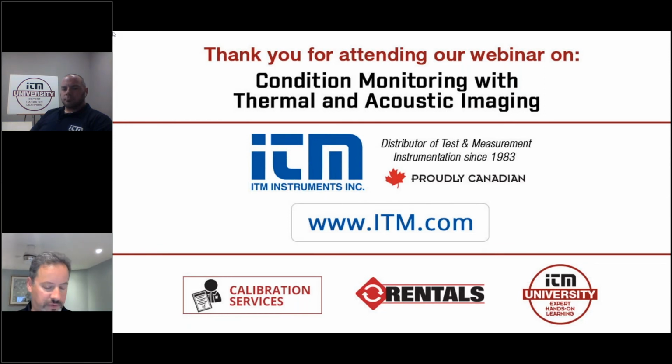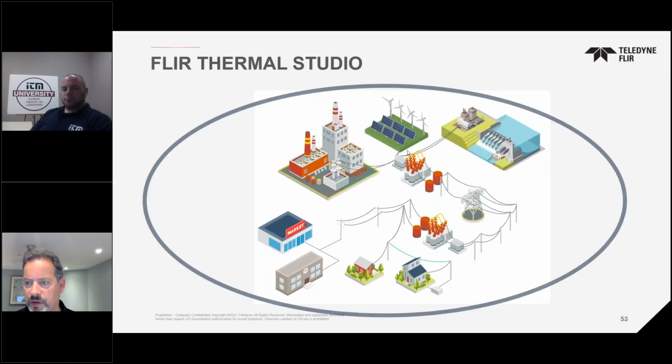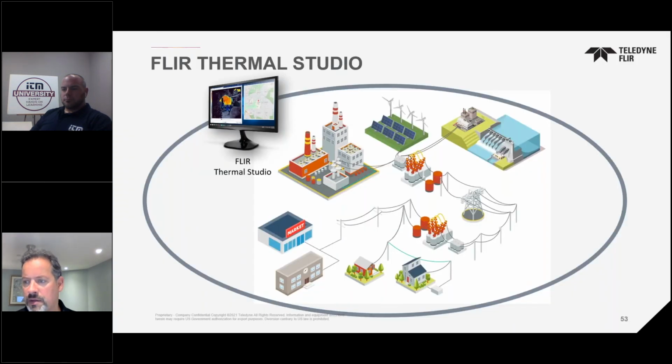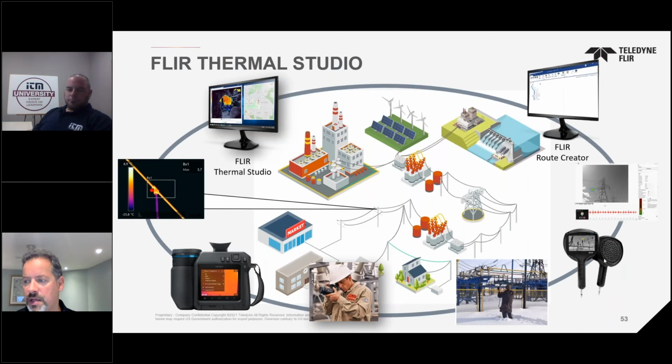If I go back to the image of the camera here, it's a handheld camera. This is a back view. Well, this is a screen. That's the front. So you see all the microphones around the visual camera in the center. 124 microphones, 2 to 35 kilohertz. You don't want to go anything above 35 kilohertz because there are different technologies out there. I'll go up to 100 kilohertz.